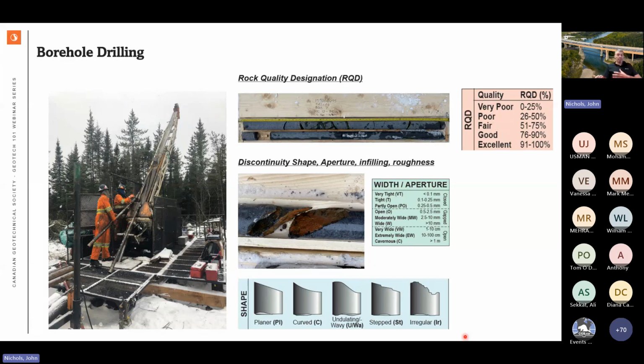Not only that, when we're using borehole investigation, if we're using a televiewer survey, which is a downhole instrument to collect orientation data, we're able to really increase the amount of data we can collect. We can compare that to our orientation data from drone or field mapping. We really have a powerful set of information to compare against each other.